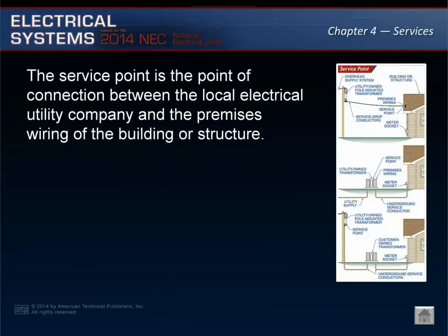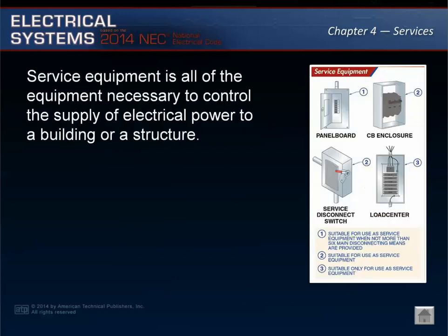The service point is the point of connection between the local electrical utility company and the premises wiring of the building or structure. An important design consideration in any electrical distribution system is the point at which the utility supply ends and the customer-owned or premises wiring begins. The NEC typically only applies to the premises wiring.